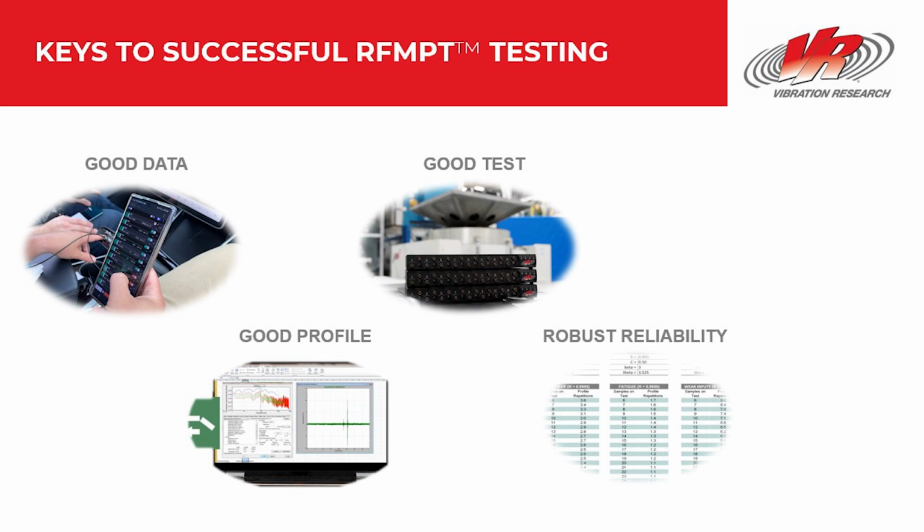So RFMPT is done early in the process on just a small number of parts to establish operational limits and destruct limits, and as time goes on, we use more parts and correlate it back to reliability. And as we get out into the field or we have late design changes, we have a baseline. We have a criteria to do an A-B comparison on any design changes or process changes that ensue at any point in the product life cycle.